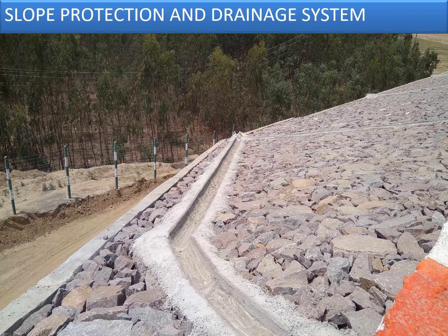You can see that these are the different types of drains which have been provided in some of the projects, but the problem associated with such drainage is that water will not move as per our wish or as per the directions being provided to it, because in this photograph you can see that the water is entering, then taking a sharp turn and then reaching the final discharge point. But during the process, at the turn which is provided manually, if the discharge is more, the water will simply flush out of the drain and hit the area which is prone to erosion of soil. So my suggestion is wherever we want a turning effect in the drainage, the turning needs to be associated with a complete circle of the drain, so that the water entering the drain will not flush out of the drain at any point of time.